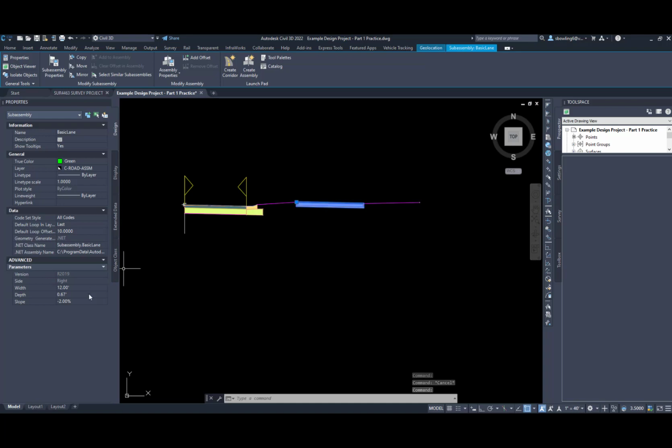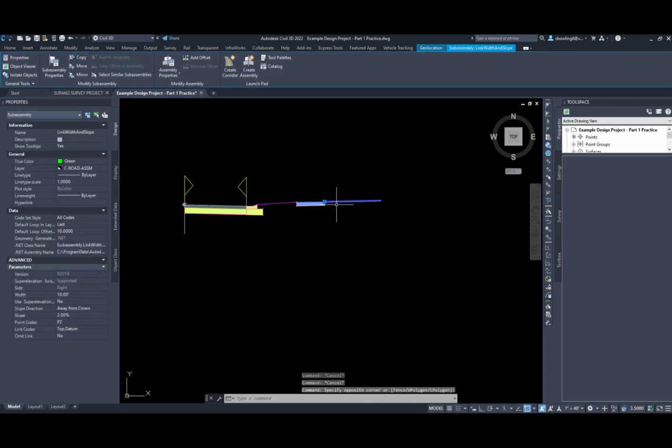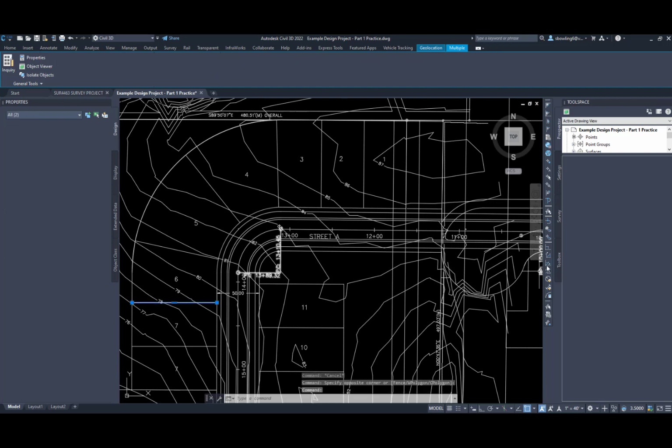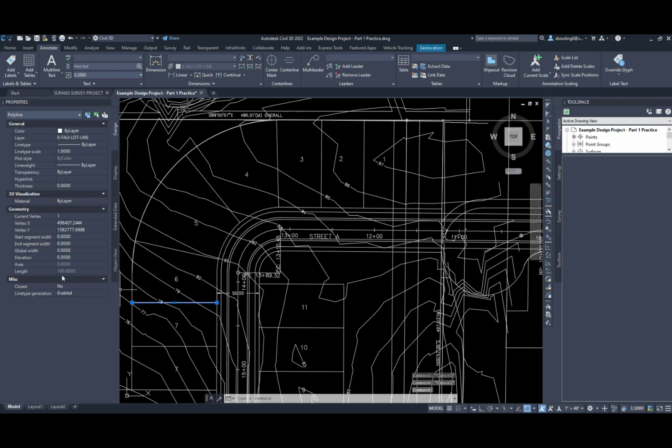All right, now this is our sidewalk. So I'm going to change that to a width of 5. And see, it's -2, it's tilting the wrong direction. So I'm going to say 2. All right, now the last thing I like to do, remember when we were talking about our lots? Let me escape out of that. We have a lot depth of 100 feet, okay?